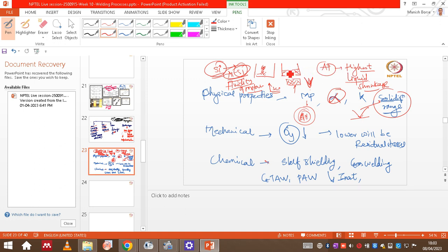So in other words, let's say we have a cavity of volume 50 cube, just for the example. Because of volume shrinkage, we have to supply extra material, right, to achieve that particular volume of the final solid plate, right? So we have to use a riser, okay, or in certain materials which have good fluidity, let's say aluminum silicon alloy.